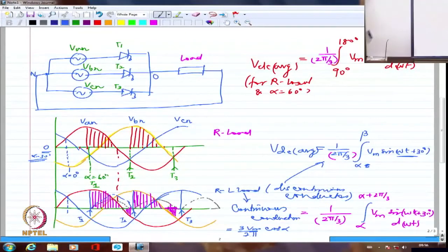Vm will be line voltage. Everywhere we are taking that to be line voltage because you will normally get some 30 degrees term. So root 3 by 2. Cos of 30 is root 3 by 2. So root 3 will come and automatically that root 3 and this root 3 will get cancelled. Please derive them. I have not derived each of them because you guys are any day better in integration and other things than I am. So please derive them. Please derive them.